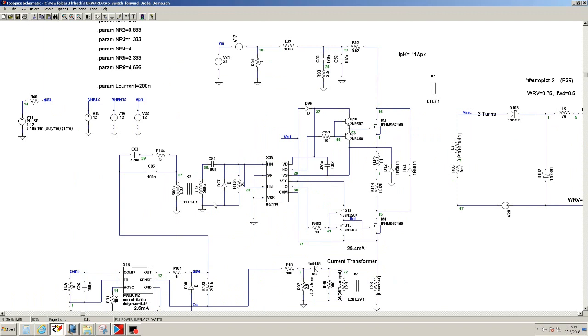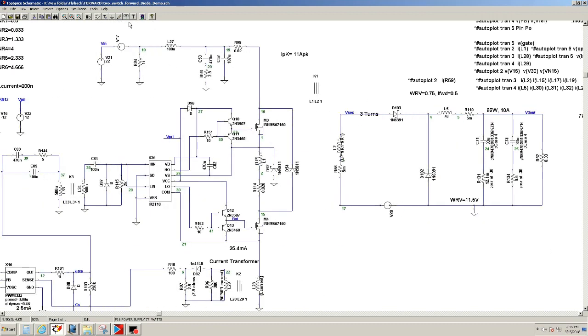in my top schematic. So here I have the driver, the IR2110. So this is the hierarchical driver. Since it only has a turn on resistance of 6 ohms, it doesn't have enough current carrying capability. So what I did is I put in these little drivers consisting of bipolar transistors to give it enough current capability. So now I'm going to go ahead and test and see how it works.